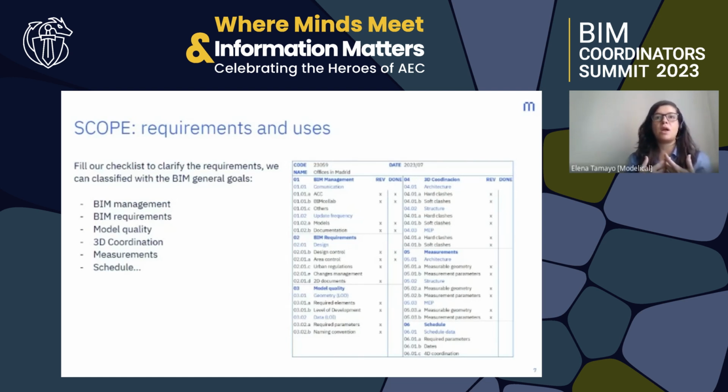For example, we need to know if every bath has a specific number and model of lights. We use Solibri to check this. This kind of check is important because the measurements are going to be more accurate, and we will have fewer surprises with overcost and delays in orders.